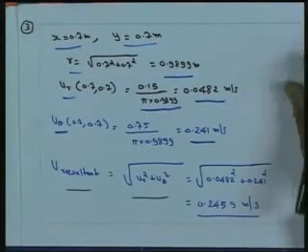So, in this particular problem we have superposed a source and a vortex. We found the expression for the velocity potential and the expression for the stream function, and then finally we found the radial velocity and the tangential velocity, and we got the resultant velocity at a particular point from them. So, this is one example with respect to superposition of a source and a vortex.